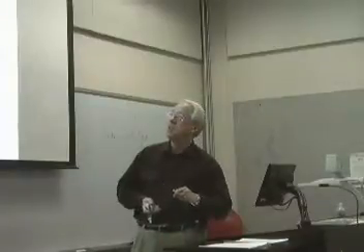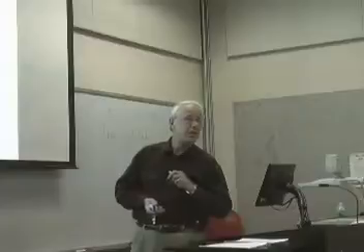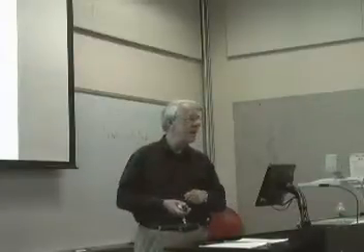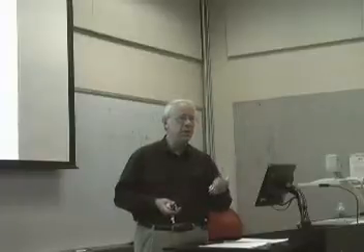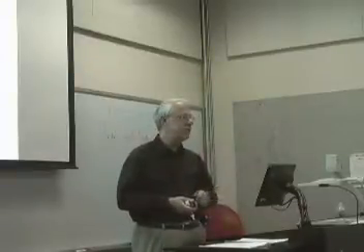That's all you're doing. So here we've established the weak statement. So that second derivative has been reduced to a first derivative. So that's right here. Here, by doing the integration by parts, you notice you pick up the flux boundary condition automatically. That's the beauty of the finite element method. It automatically brings in flux boundary conditions. And if you do nothing on the boundaries, it assumes that every surface is adiabatic, 0 flux.